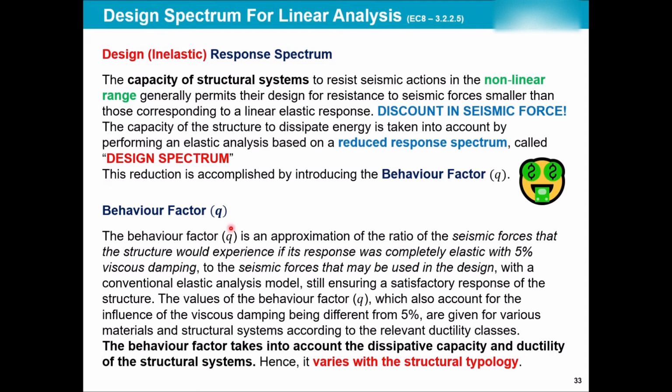Again, lower acceleration means lower force, which means lower section dimensions, which means more space, less material use, less time of construction, more money saved, happier client. So consider the behavior factor as a discount, a behavior discount point that the code allows us to do.